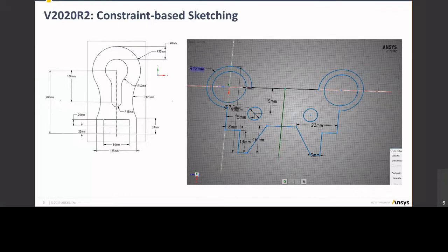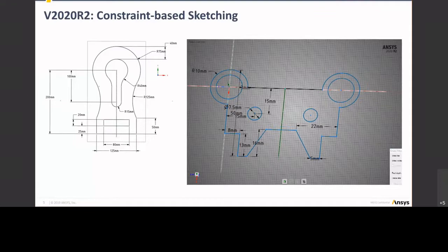And you can see this quick video is just changing the outer radius of that top left-hand circle between 10 and 12 millimeters. But you notice the distance defined between the inner and the outer circle is 3 millimeters. So you can see that's consistent, and the other constraints are constraining it within the geometry. So it's keeping the edge of that circle with the horizontal line as perpendicular.